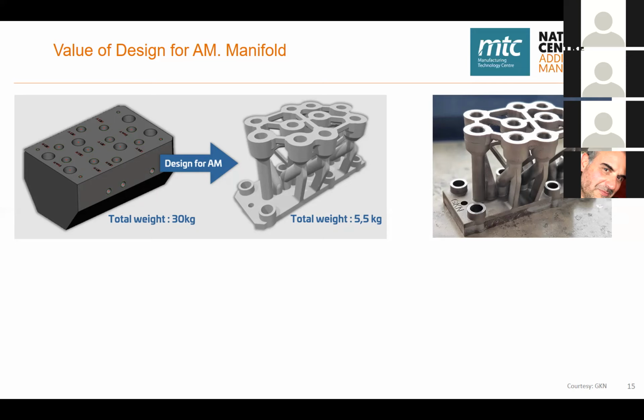And we say, okay, yeah, that makes sense, because those guys are doing aerospace components. In aerospace, it's important to have lightweight, because then you spend more money on flying planes. But when we in reality think about it, even if on the right image we see a block of metal, in reality, all the technologies in additive, or almost all of them, use a discrete head, or a single head, or a laser, or an electron beam to create the components. That means that we have a very thin laser, or very thin head, creating each one of the layers, and many layers for creating a component.